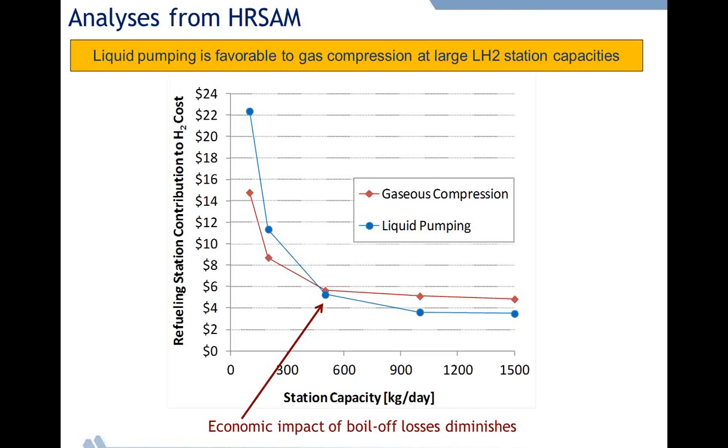So if you dispense a few kilograms and then you lose 50 or 60, then it is a major implication. So for liquid stations in early market, we see some designs that will opt to use the boil off, put it in a buffer storage, and even use some pre-cooling to dispense into vehicles. Of course, this is more capital, but it is really a trade-off between losing a valuable molecule versus putting more capital on site. And here you will see the trade-off, and you will see a certain demand level in a given day, the impact of the